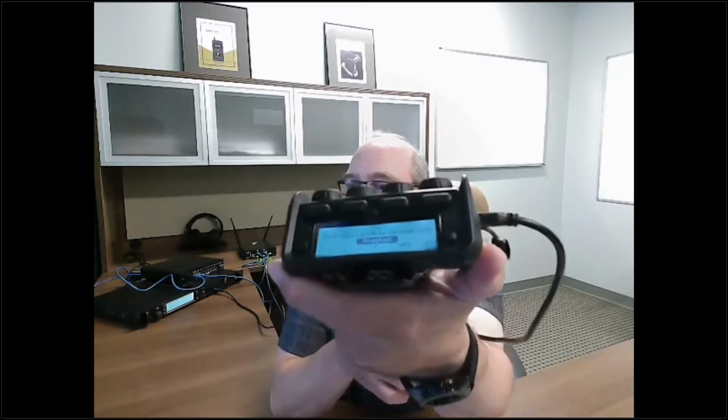One other good thing to remember is all of your firmware has to match on the system. So if I have a big rental system or something that's going out, they all have to be on the same firmware. In this case, it's 1.8.0.3. But when I plugged it in, it said checking the firmware, and then it gave me this screen here.